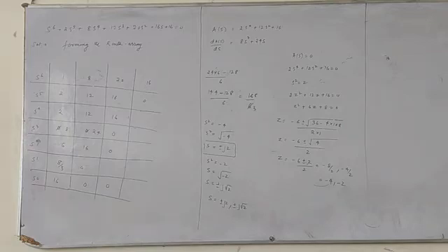What does this indicate? You should know. Oscillation. Pure sinusoidal oscillations will be there. This will indicate the sustained oscillations. So we will call them the frequency of the sustained oscillations. So you write down this point.